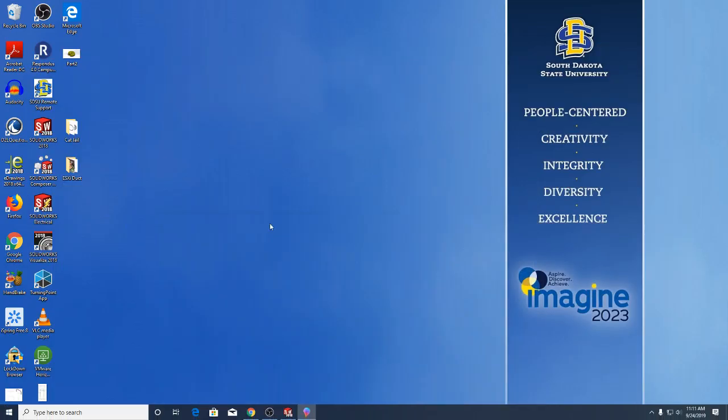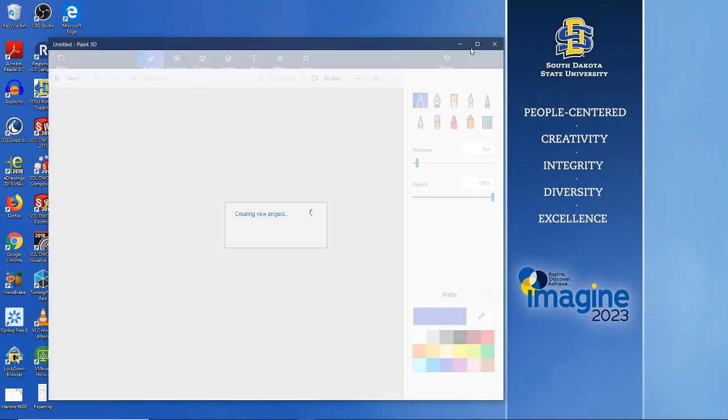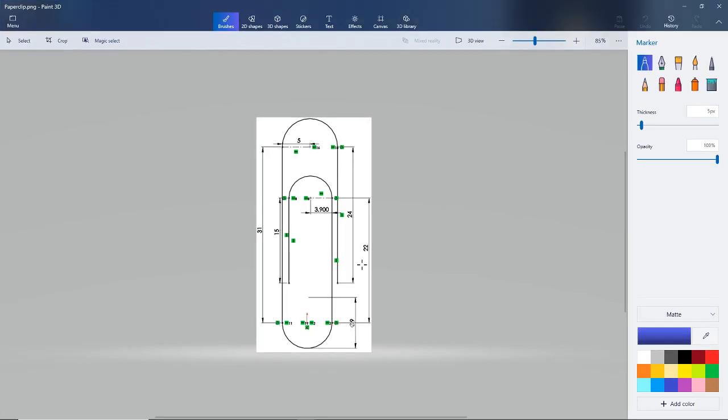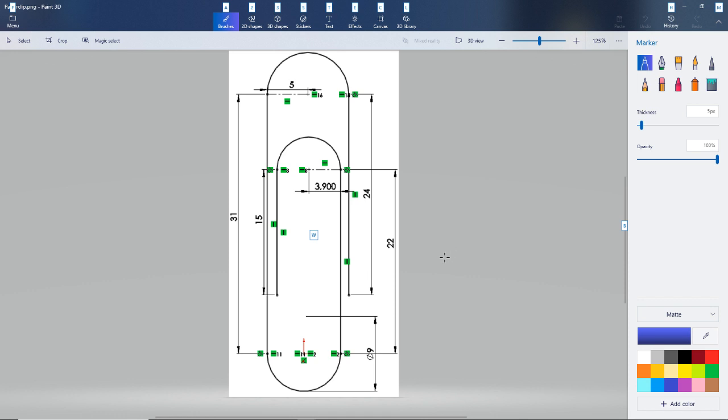Let's try to use the standard dimensions for a paperclip to make a paperclip. So this is the metric standard for a paperclip. The diameter of the steel used is a little bit under 1 millimeter, and these are the dimensions. So I'm going to draw this shape as a sketch representing the path to follow, and because the cross-section of a paperclip is a circle, I don't have to worry about trying to draw a secondary shape.